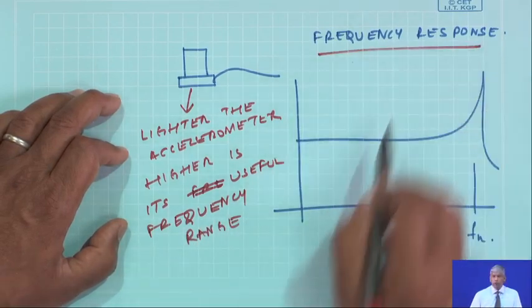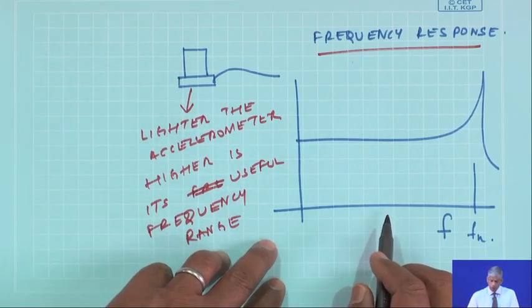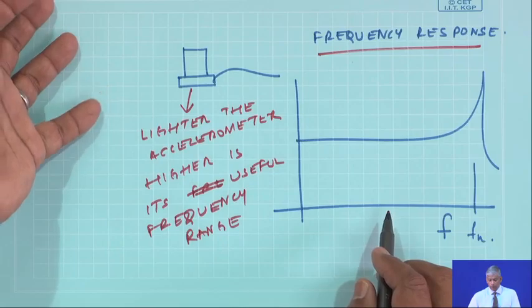So, make sure that you have the right kind of vibration based accelerometers to measure cavitation, because it is a very high frequency vibration.